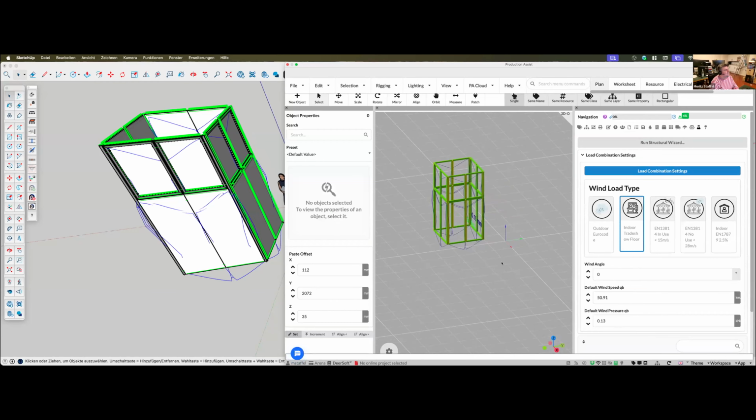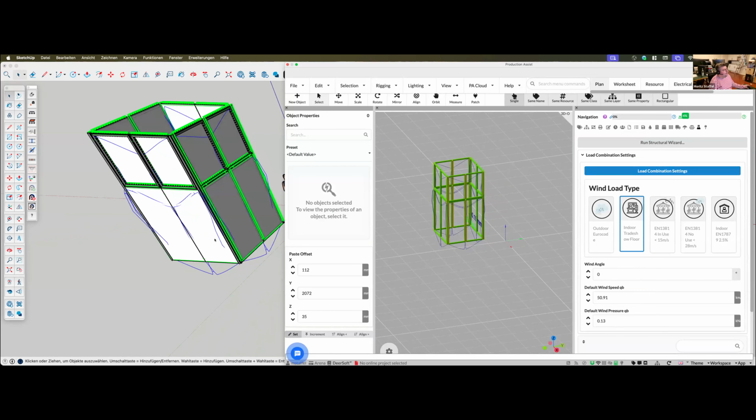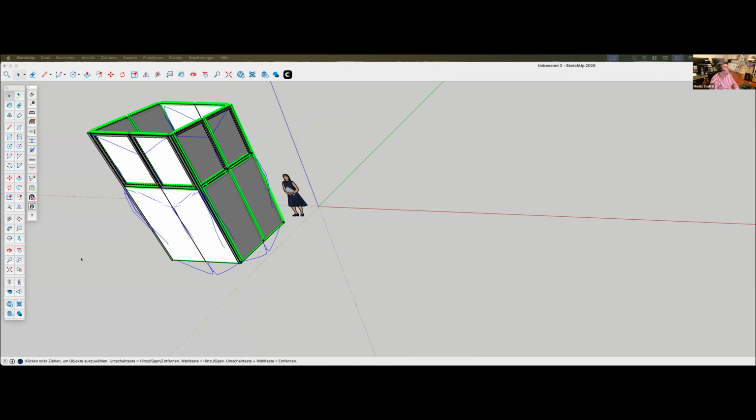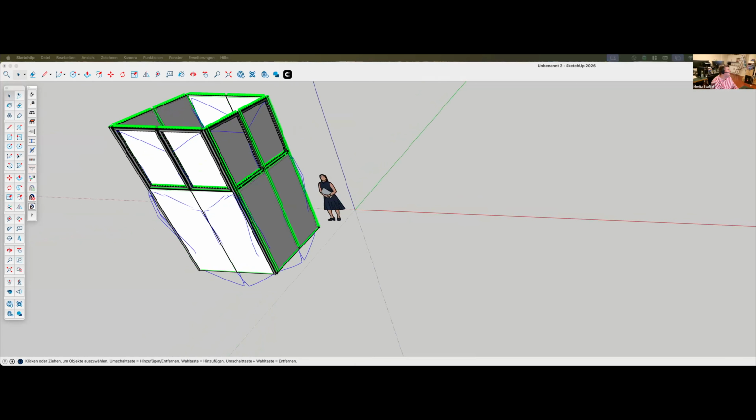This is because you still need to define the actual area that gets affected by this. To do this, let me move this to the side, that's a little bit easier to see, you need to use the wind load button in here. It's a small wall with a wind load. You click it, and then when you click in the drawing, it allows you to draw a polygon like this, where you can define the affected area.